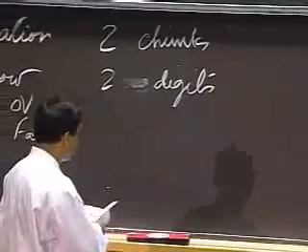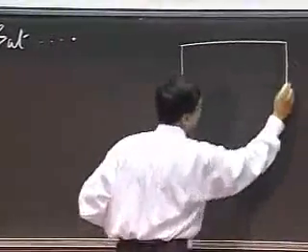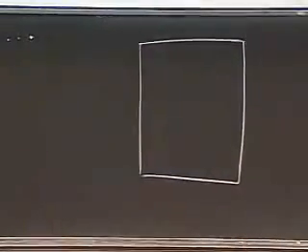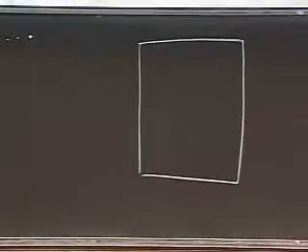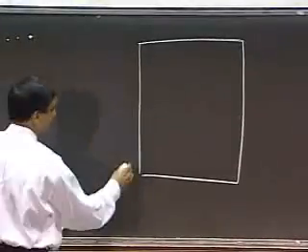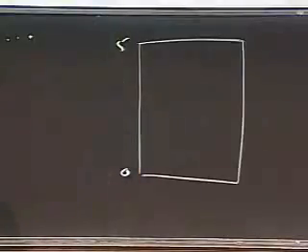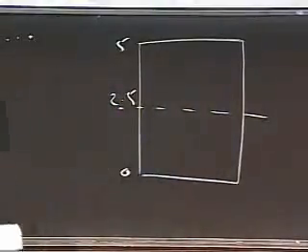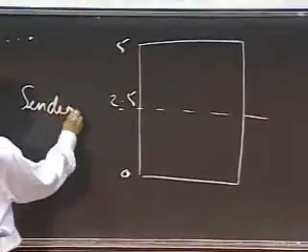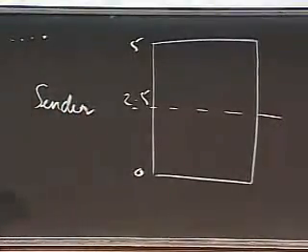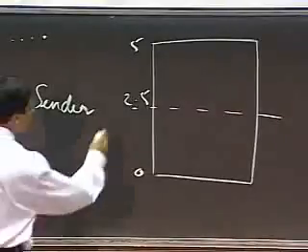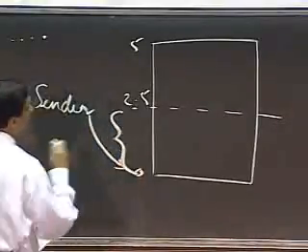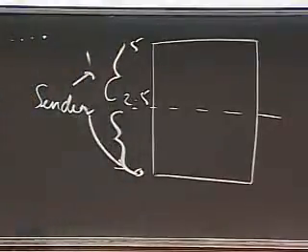If you look at that signal there, what I ended up doing was creating a design space that looked like this. This is on page 6. I said, well, the range of values is 0 to 5. At 2.5, I drew a line, and I said, as a sender, if you wanted to send a 0, then you would send a value here. And if you want to send a 1, you would send a value here.